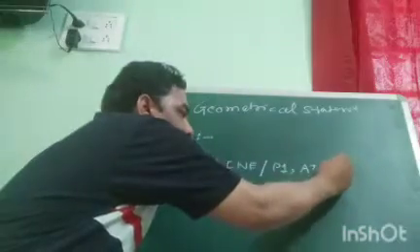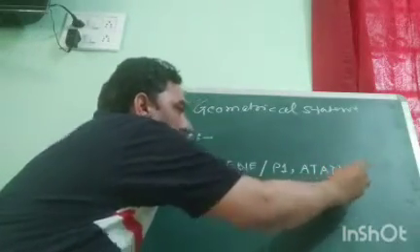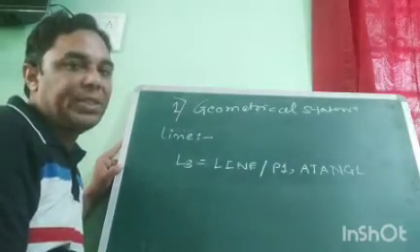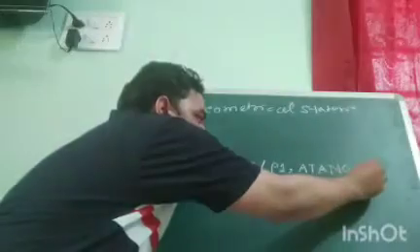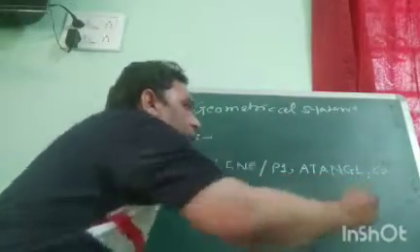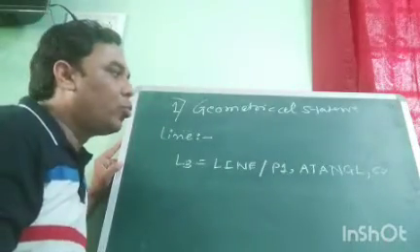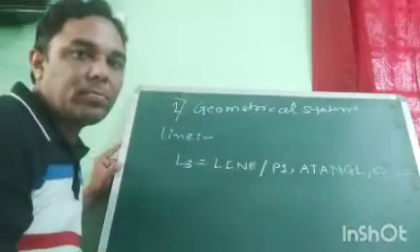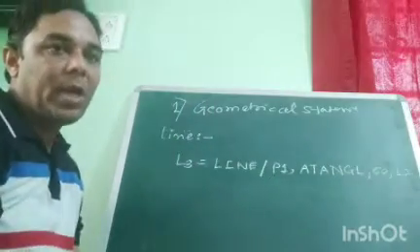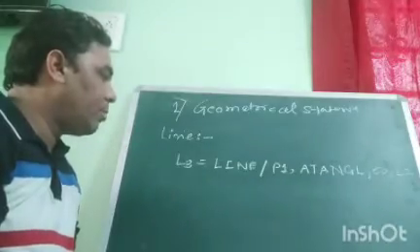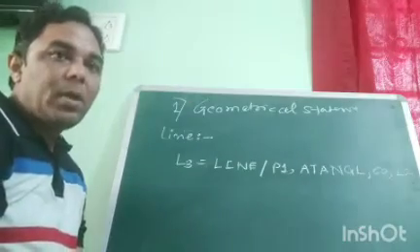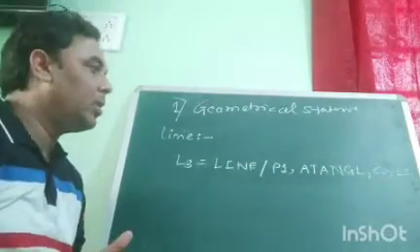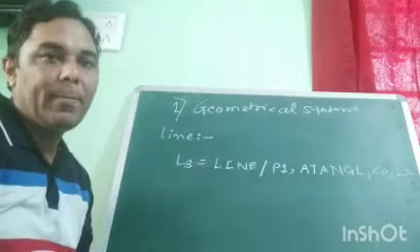ATANGL. Not an exact English term, but we need to memorize that word as it is. So what angle does it form? A 60 degree angle. And to which line? To the L2 line. So the interpretation of that particular syntax coding is that the L3 line forms a 60 degree angle and passes through the point P1.